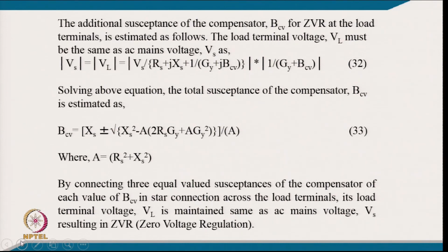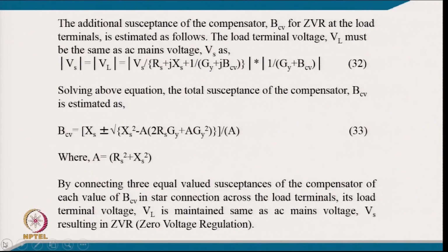With this, we would like to conclude today's lecture. So, what we covered here: passive compensators, typically for single phase, for power factor correction at the load terminal, power factor correction at the substation, and then zero voltage regulation at the load terminal for a single phase load. Then we derived the relations for the 3 phase 3 wire system, which may have a star connected unbalanced load or a delta connected unbalanced load, converted to an equivalent delta connected unbalanced load. We first compensated the power factor of each line to line, then we provided load balancing, and after providing load balancing and power factor correction, we got the compensator design for unity power factor, and this delta connected network we converted to an equivalent star connected admittance. From the star connected equivalent per phase circuit we were able to get again the zero voltage regulation conditions for the 3 phase 3 wire system.